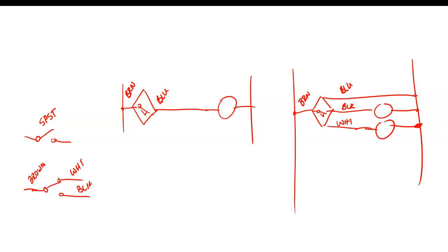The inductive sensor, when it was generating a trip, still dropped around 4 volts because it needed it to operate, right? Understand? Get power to operate. But that leaves us 116 volts, which was well within the limit of that sensor rated 120 volts.